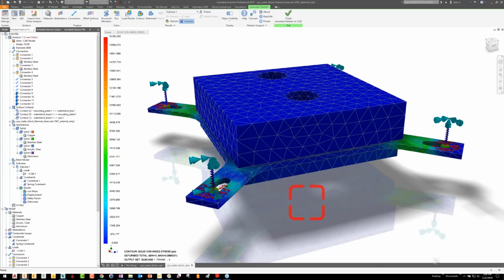So I'm going to have a pretty steep thermal gradient, and the parts that are made of different materials are going to expand and contract at different rates due to their individual thermal coefficients of expansion and their individual temperatures. So as they expand and contract, they're going to start to fight one another, especially the ones that are bolted together and they're made of different materials. You might see them fighting against one another at that bolted connection, parts getting squeezed, parts getting pushed away. That's thermal stress is what we're looking at here.